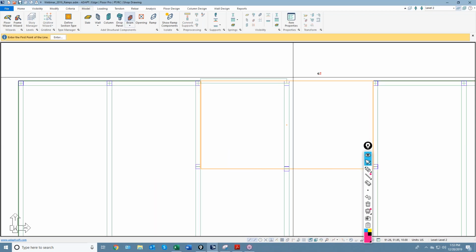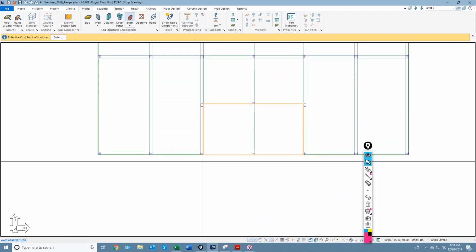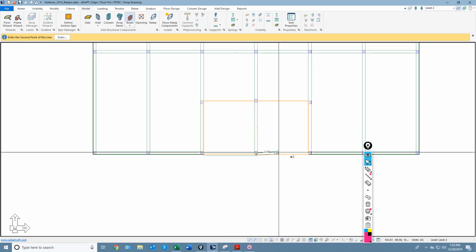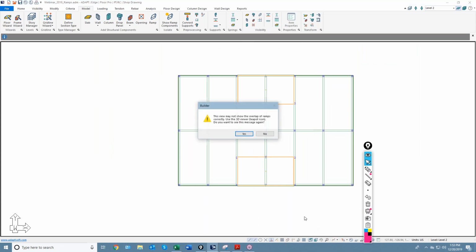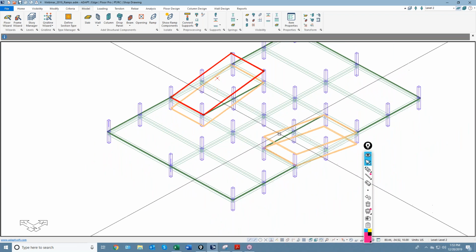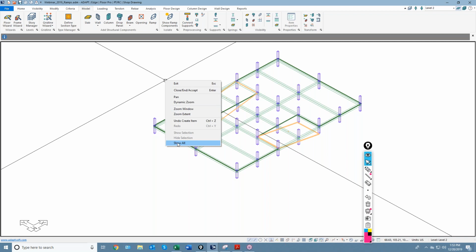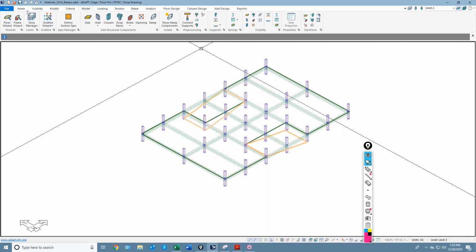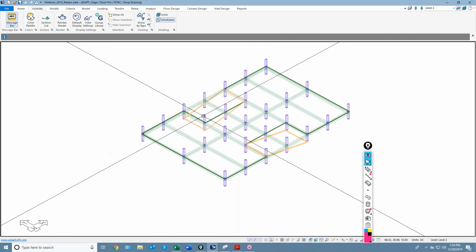And I'll also add something that looks like this. And I'll show this on just this one level here. Okay, so if I go to a 3D view, you can see, by the way, I'm going to select those 2 ramps. If I right click, there's now hide and show selection. Just, you might be interested in that. I'll hide that, and I can right click and show all. So that used to be done only through visibility. That's now a right click option. We're adding more options there.